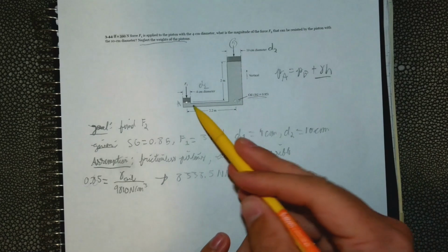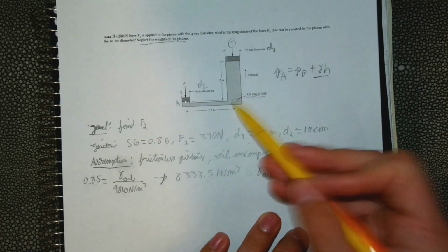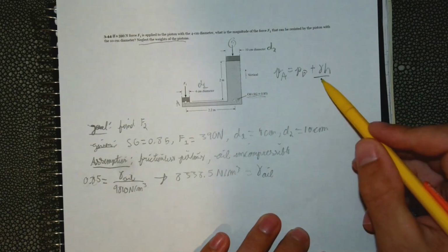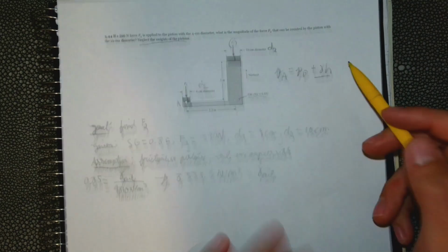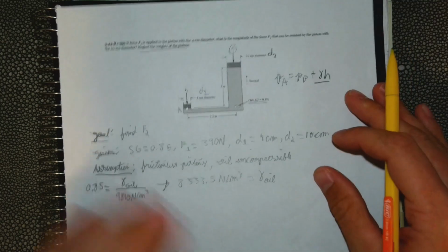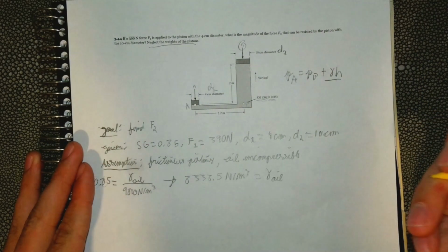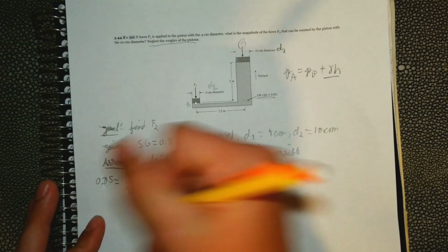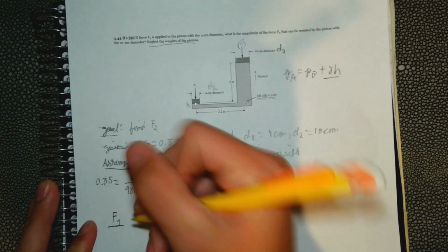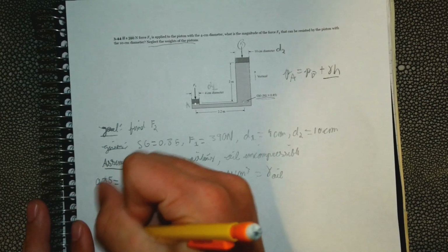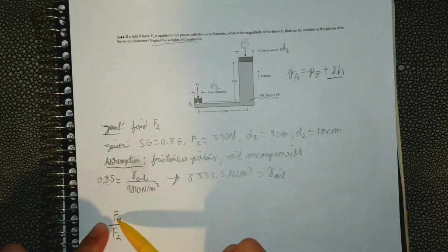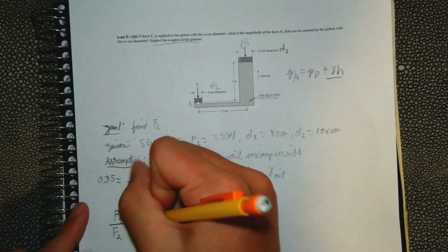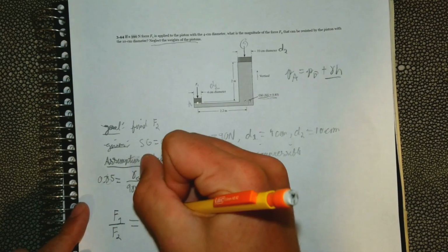Back to what we were doing, we know that pressure A here will equal pressure B plus specific weight times height, right? Using that planar interface rule, and then using that pressure equation I just derived. Okay, so this is going to be helpful. We say that F1 over F2, so the force of the weight of piston 1 over the force of the weight of piston 2, will equal